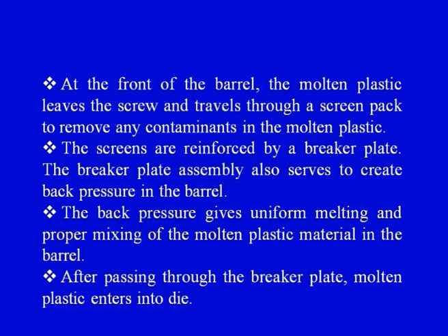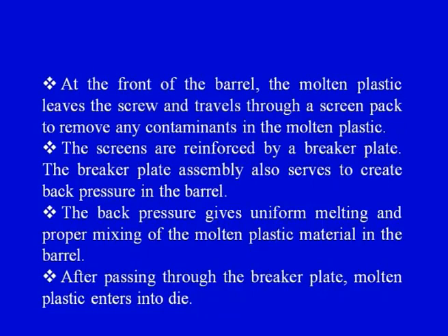What is the role of the breaker plate? The breaker plate assembly also serves to create back pressure in the barrel. So, we need to create a back pressure in the barrel. Why the back pressure is important, we will see in the subsequent point. The back pressure gives uniform melting and proper mixing of the molten plastic material in the barrel.